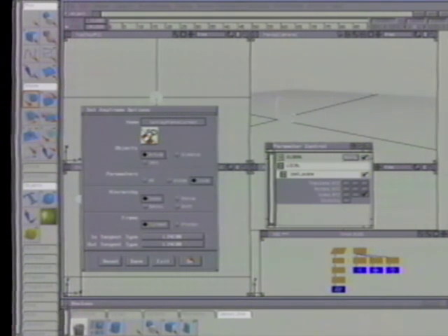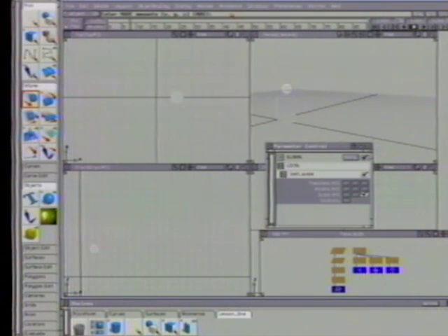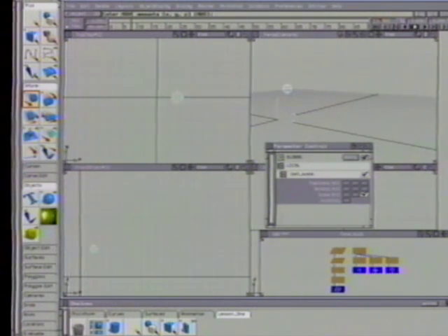Change the in-tangent and out-tangent types to linear. Earlier, you changed the tangent type in the Action window. You can also set the tangent type before capturing keyframes. Click on Save. In the time slider, go to frame 8. Select Set Keyframe.